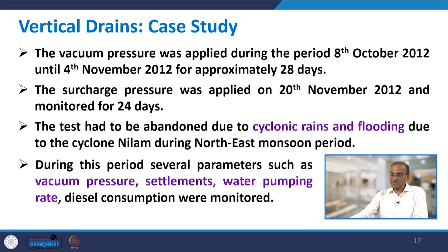The vacuum pressure was applied during the period of 8th October 2012 to 14th November 2012. That means approximately a month, about 28 days. The surcharge pressure was applied on 20th November 2012. So the first treatment was done using vacuum pressure, then on 20th November the surcharge pressure was applied and monitored for the next 24 days.